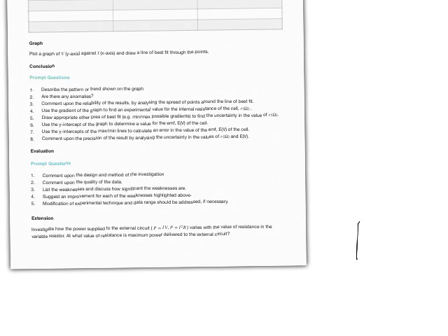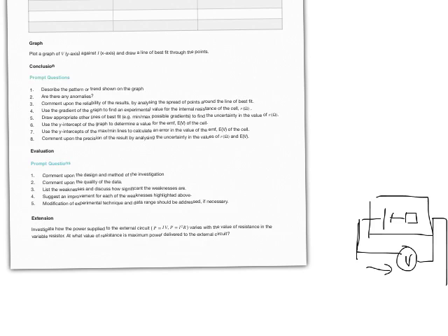What else? If we think of our circuit, there's always the old favourite. Our voltmeters, they don't have infinite resistance always. They draw current away from the circuit. So you could also say, or you could argue, the voltmeter has resistance. It's not infinite, and so also affects our results.